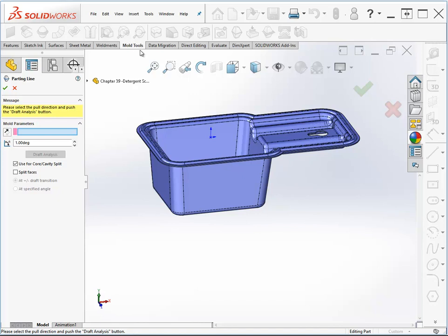The mold die is going to involve certain things like cooling lines. You're going to have a lot of bolts, runners, sprues, injection bushings. You may have a multi-cavity die. The mold die could be the size of a VW, or it could be something smaller that would fit on a desk.